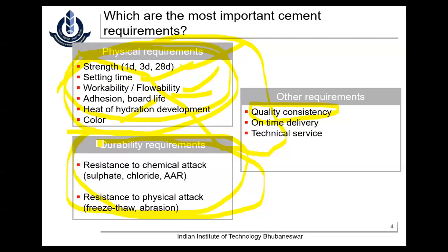Now when you were talking about high performance concrete, the scenario was different. But nowadays, the new thing coming up is, recently I was interacting in Mumbai in January, I went for a program. They're talking about how even if you make a 20 megapascal concrete, it should have the highest durability. Even if you make a 50 megapascal concrete or a 20 megapascal concrete, it should be of high performance. That means the definition has changed. The definition of high performance concrete is that it should have the highest durability for any given strength. The things have changed dramatically.